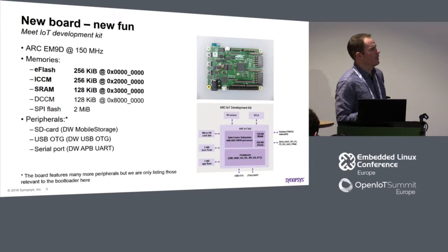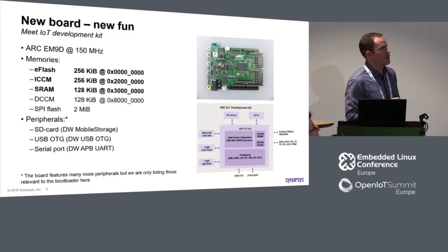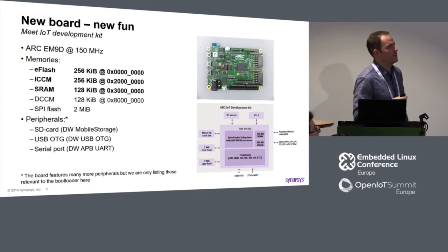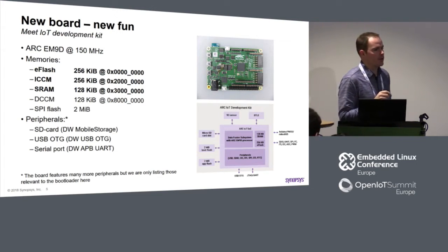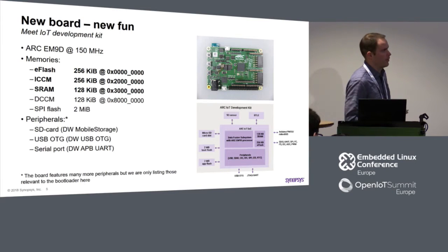And so then here comes DCCM, which is pretty much the same as ICCM, but this is Data Closely Coupled Memory. And there is one but very important difference between them. DCCM is not connected to the instruction fetch queue, which means we cannot execute code from that memory. And which means this is random access memory, but it is not very flexible.